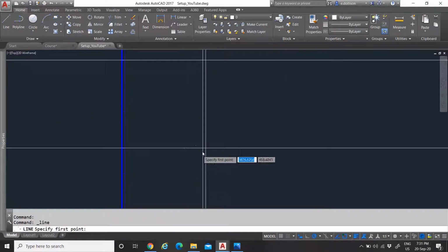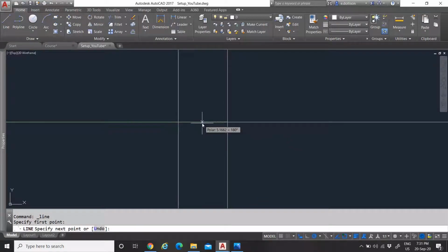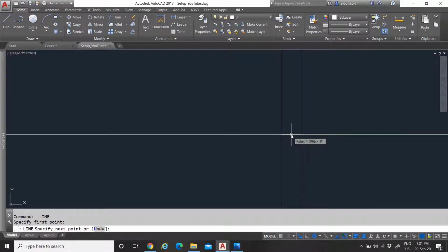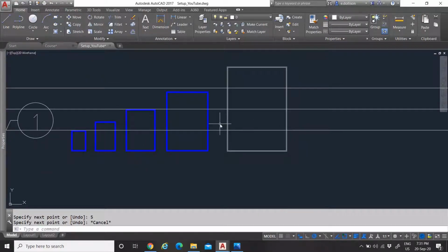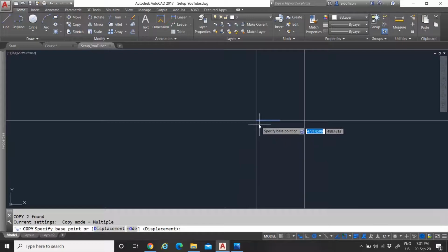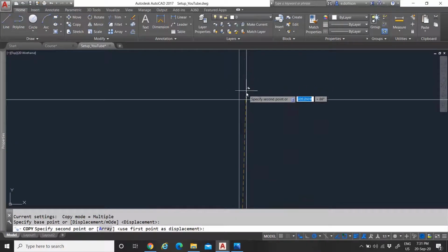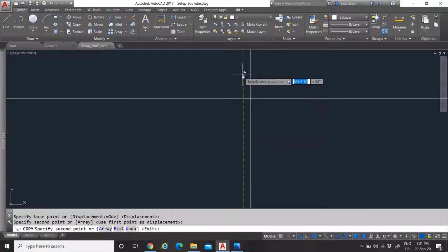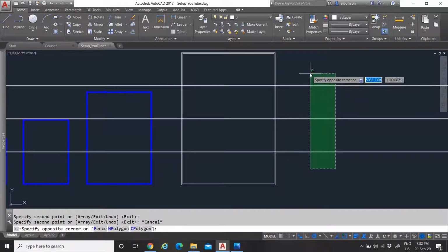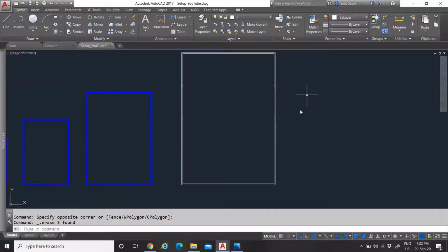Now our lines once more on the inside. This one would be 5 millimeters, 5 millimeters. And then we will copy this a couple times. Copy, CO, corner or end, and we will copy it all every time we have a construction line. Our construction layer is very helpful. Okay, these you can now delete because you won't need them anymore. We have all our heights for all our paper sizes.